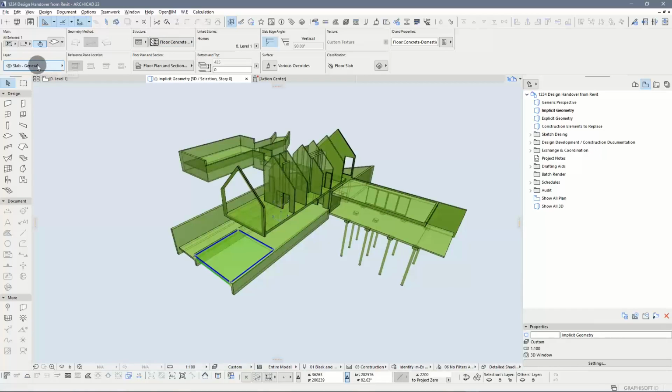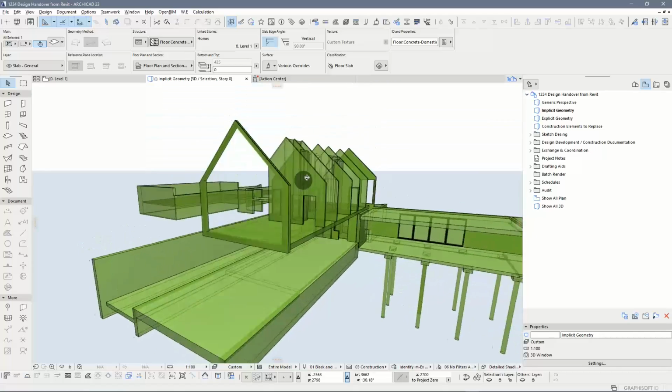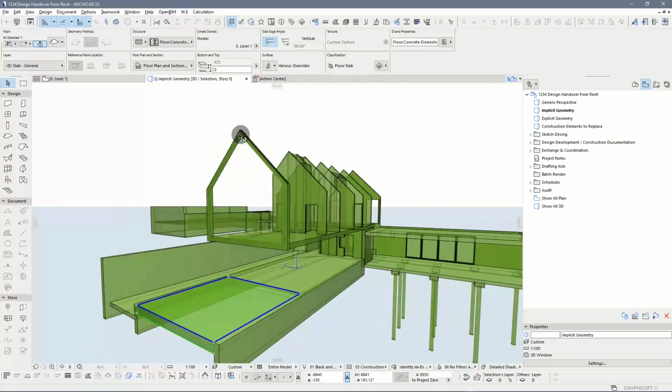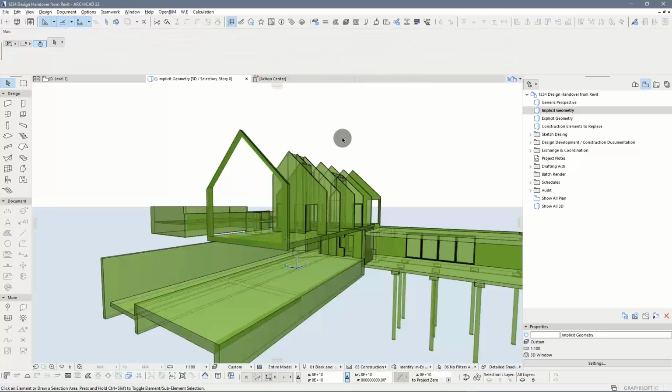They're already landing in the right layer that I've chosen for them, and they have the right classification. So it's easy for me just to take over that without much modification, other than adjusting line weights and some other things. Even this element in here, which is an actual wall with a bunch of cuts or trims through it, has come through as an actual wall with a composite. So that is possible.